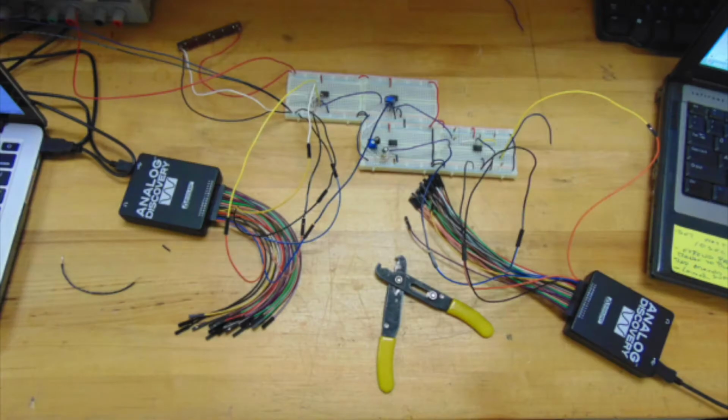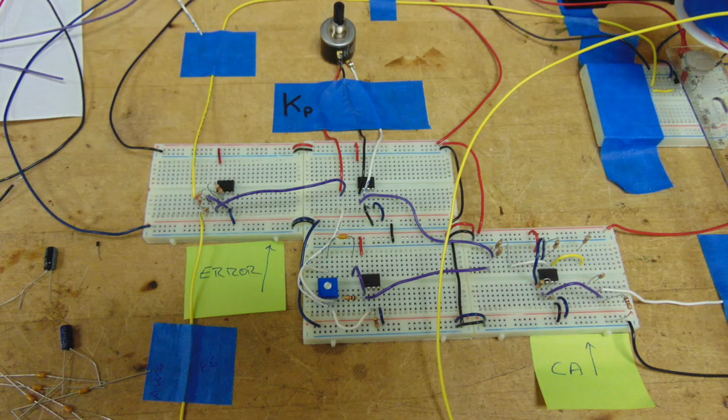The Ziegler-Nichols closed-loop tuning method is the method that we use to tune our PI controller. To use this method, remove the integral function from the controller. Gradually increase the controller gain until the system starts to oscillate. The set point may need to be adjusted to create a disturbance to start this oscillation.